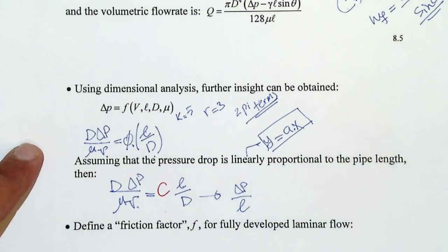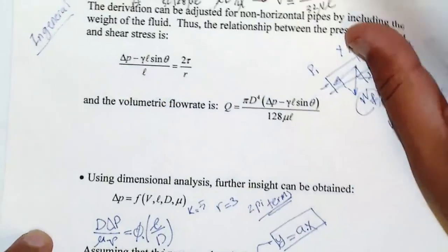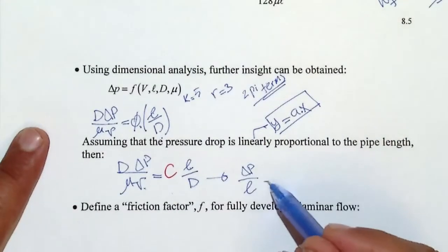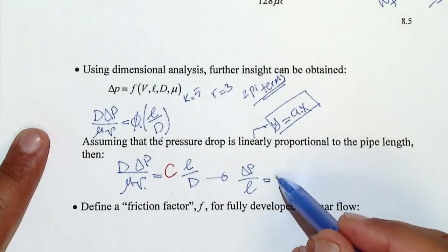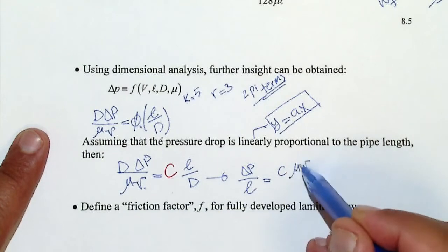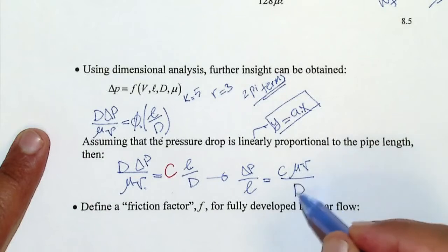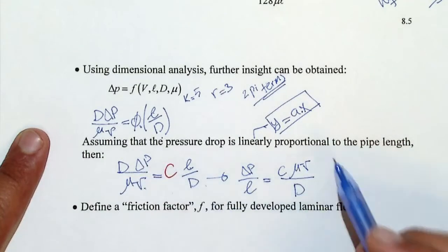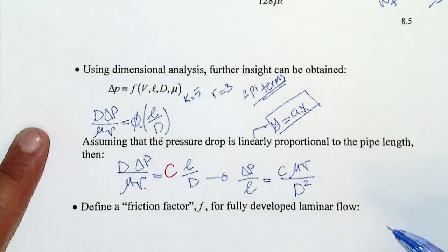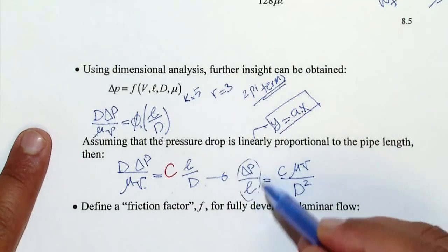What is the pressure drop per length of a pipe? The same that we did here, we also have delta P over L. So we keep delta P over L here, and the rest is going to be C mu V over D squared. D and D multiply by each other, so D squared. Okay, this is going to be your pressure drop